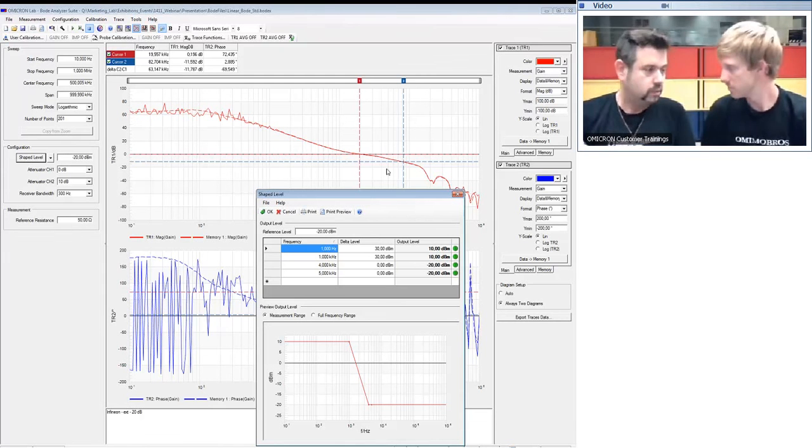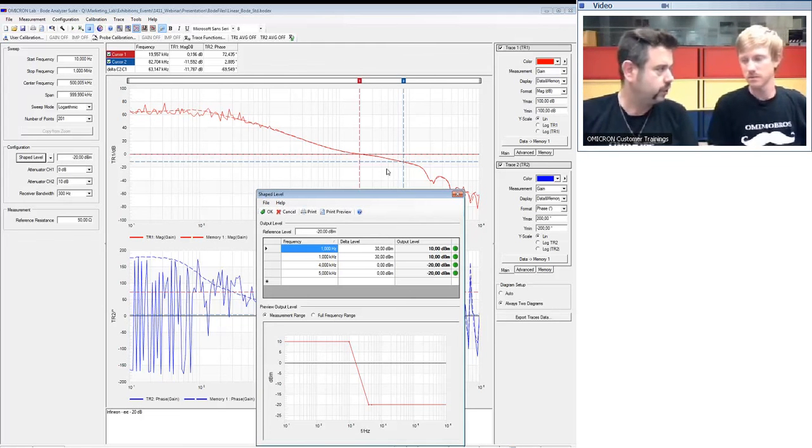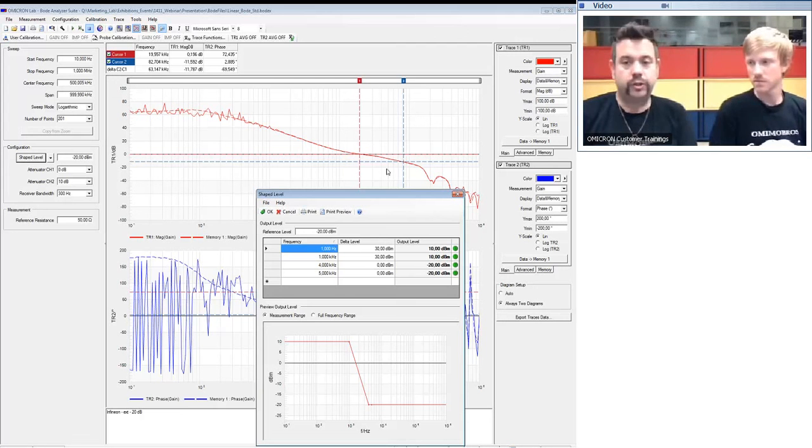But anyway, if you have the possibility to play around with a compensator, for example, in a digital system where you just reprogram your controller, or if you have access to add or remove capacitors, then you can do this and perform a measurement before and after, and you see directly the influence of your change on the loop behavior.